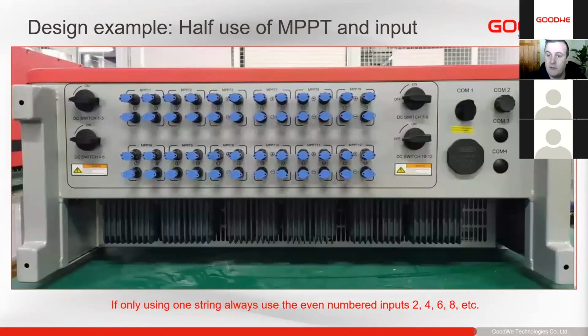And just a nice view for you of the bottom of the inverter, just to show exactly what we meant. So you'll see input 1 and input 2. Input 1 has that 20 amp current limit, and input 2 does not have any current limit besides the MPPT current limit. So in this case, we can use 2, 4, 6, 8, 10, 12, and so forth. That's if we are combining strings or using more than 20 amp strings. Luckily our module guys aren't there yet, but who knows, one day they might have modules that give us 30 amps, so then we'll have to use one input.